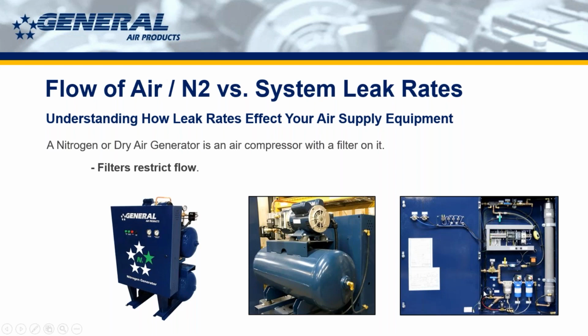But before that, we need to condition the air to make sure that there's no oil or water or any particulate that gets to the membrane, or else the membrane will be destroyed. So those 3 need to be changed annually, just to ensure that they're always working. The membrane, hopefully you only have to replace that every 7 or 8 years, because that's pretty expensive.